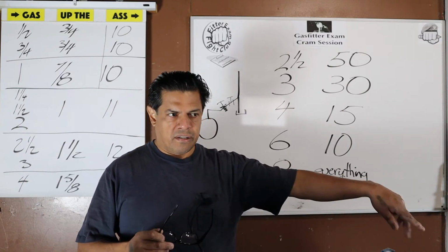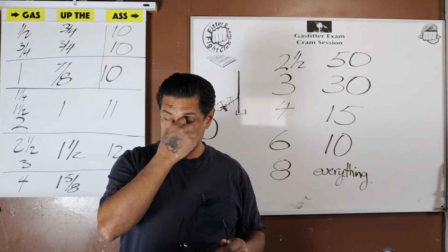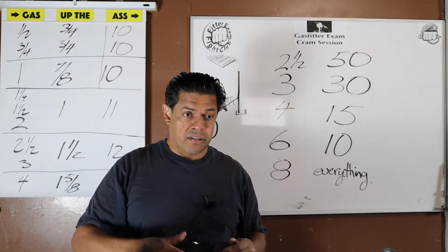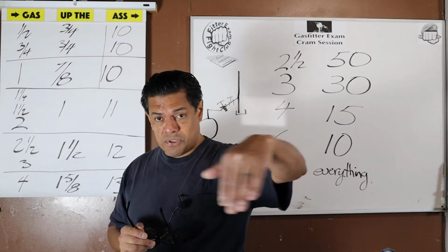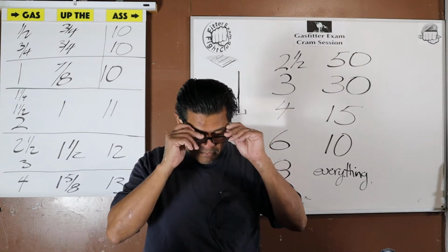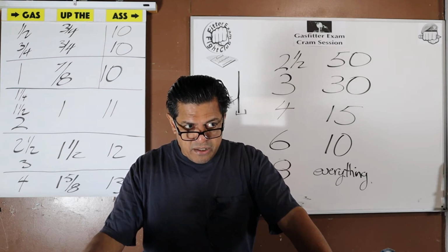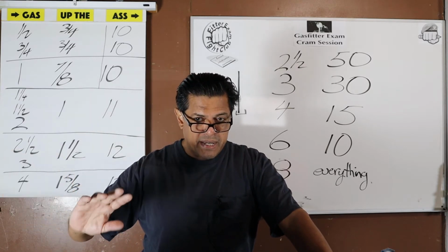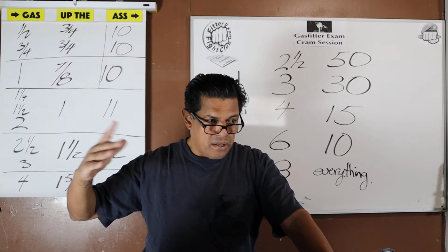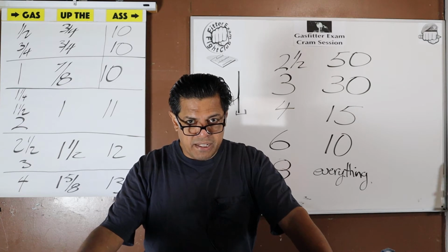The yellow spray paint on the street marks the mains, and if you're lucky, you'll see 15 psi. Sometimes they'll even show the sizes, 6-inch main, and then service here, 2-inch service, whatever. Okay, but plastic. And this is PE piping, not yellow piping is plastic. It's polyethylene. It's not PVC like you would use in waste. It's not PEX like you're going to use in a radiant floor. This is PE, polyethylene.